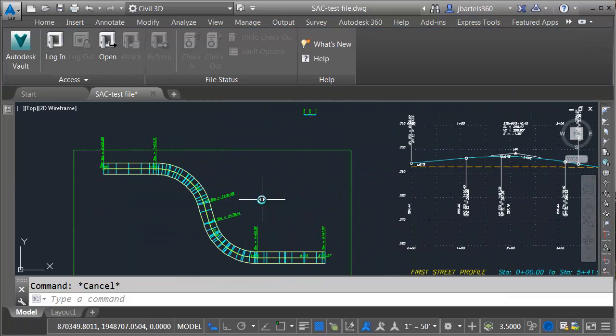So as you can see, very easy to go through and create a custom part if you want to. We have at this point looked at how we can create static objects, we can assign variables, we can assign targets, we can assign super elevation. In the next session, we're going to go back to our part and look at a few more advanced concepts. We'll add some custom daylighting.